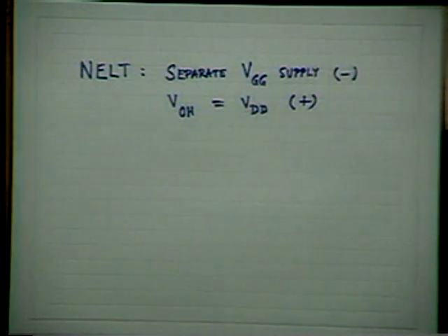And now, another good thing about it is that to adjust the noise margins, to improve the noise margins, I can play with two parameters. One is the geometry factor beta R, and the other is called a biasing parameter, which is a function of VGG and VDD. We shall be discussing that afterwards. So two parameters come in.